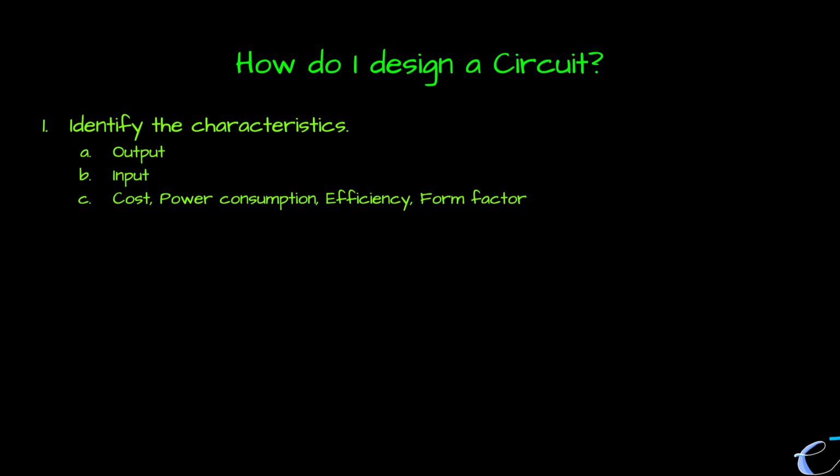Same thing with power consumption and efficiency. What kind of cooling do you require for the circuit if it's going to be used for longer terms? What kind of components are you going to use? Are you okay soldering surface mount devices? Do you need through-hole technology components? There are many such considerations which will come into effect when you're designing a circuit. These three are the most common ones which I use when I design my circuits.